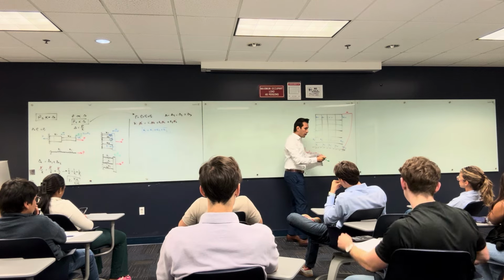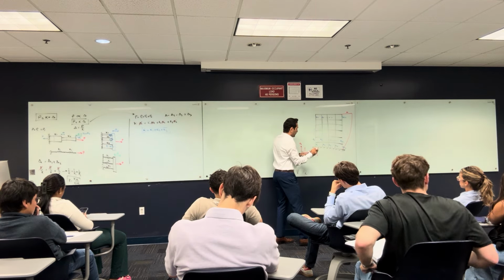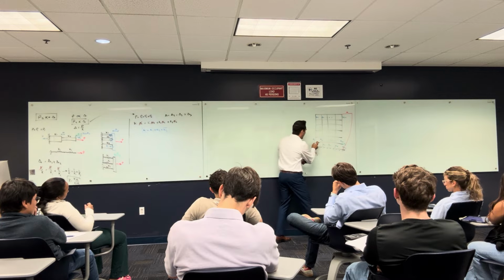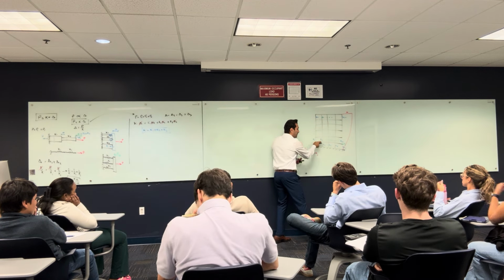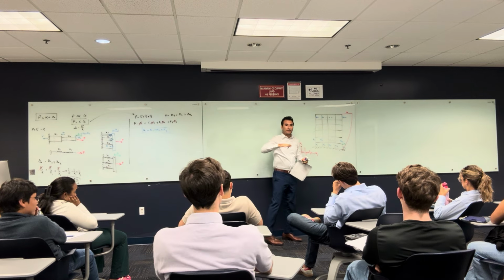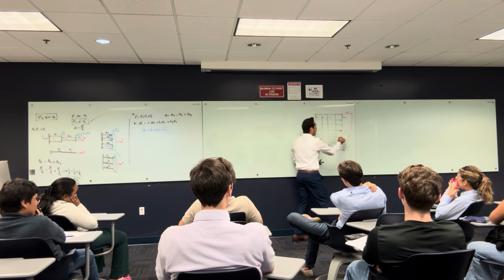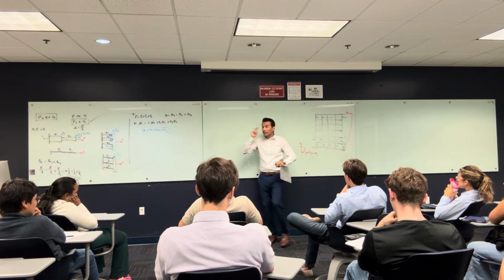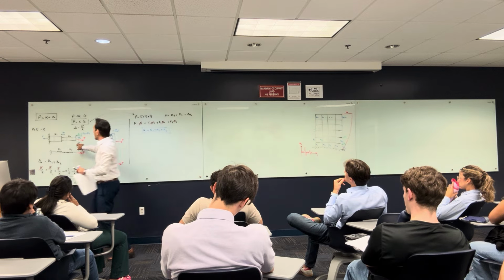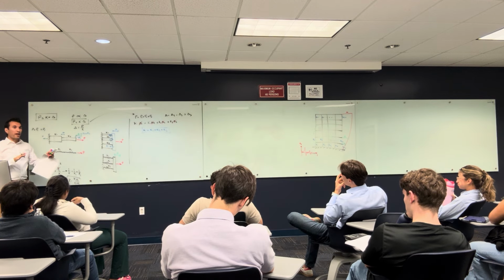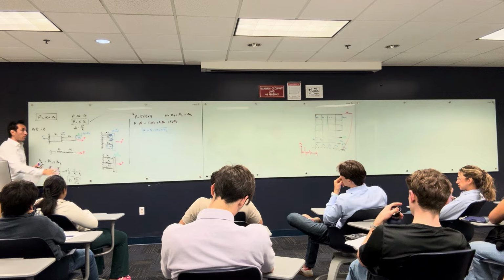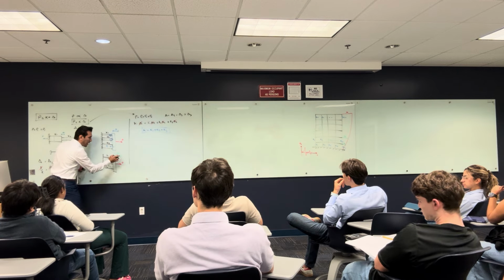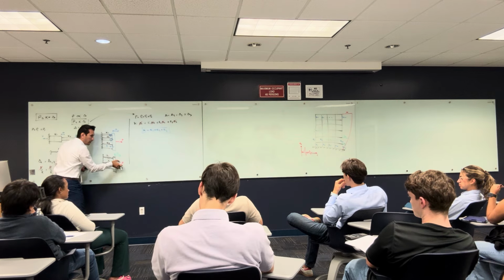So if this slab moved, let's say delta 1 here, what does that mean for this column? This column shifted delta 1, this column shifted delta 1. All of them had the same deformation. Same thing here: this story has delta 2, so all the columns have the same delta. This is going to remind you of which system: stiffnesses in parallel or stiffnesses in series? Sure, parallel. This one is parallel. All these stiffnesses have the same delta under the same load.